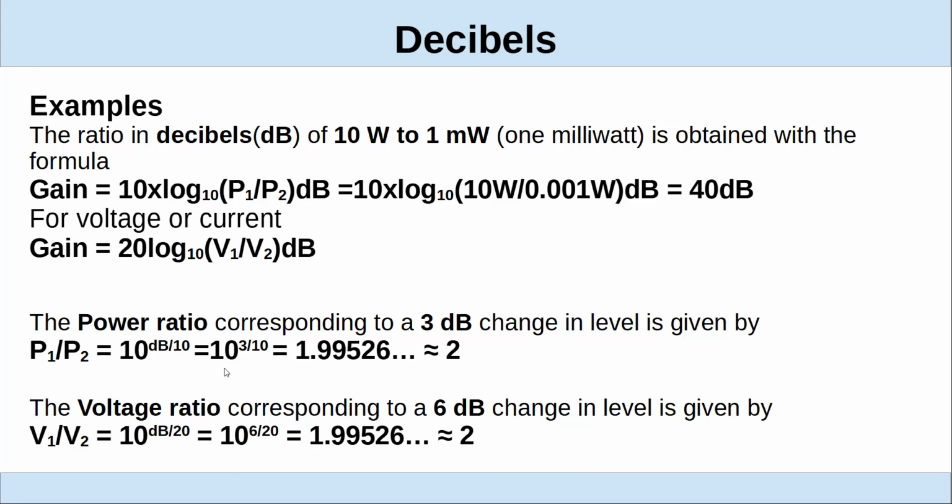And it's just a matter of taking 10 to the whatever that dB value is, divided by 10, because in the formula it's 10 times. So we're going to divide it by 10, and you need a calculator for that one, and it'll come out approximately 2, because 2 isn't exactly 3 dB. It's 3.01 something. To confuse you.